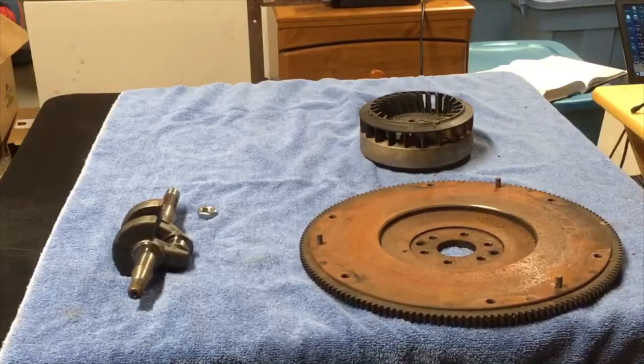So being that it was lighter by basically half, it's got much less mass, a lot less inertia. So as you saw in one of the other portions of the video, it speeds up faster or it accelerates faster. There's a performance component that comes along with that. The downside of that is that in a car application, when you try to take off from a stop without having that extra mass of the flywheel, it can take a little more throttle or whatever and a little more clutch slippage to get the car moving.